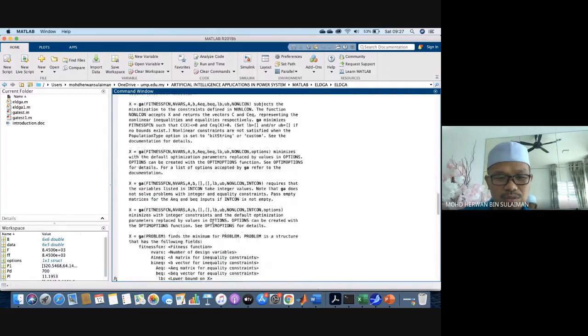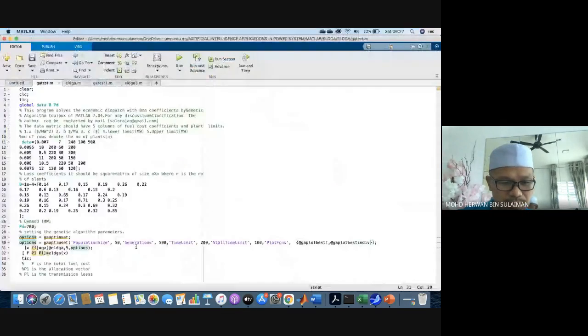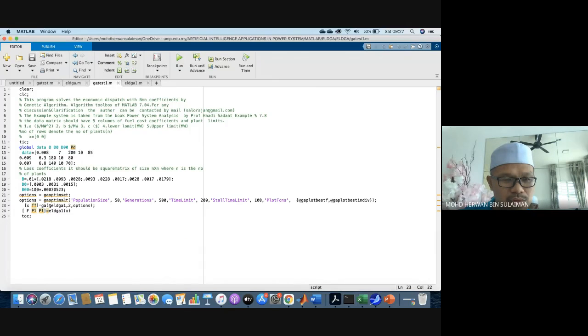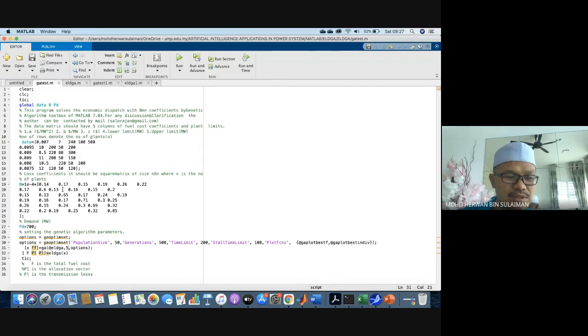Okay, so let's take a look back at what this guy has done. It's just 5 and options. What are the options we embedded here? I'm not sure what the 5 is, let me check. Because we have 6 generators, right? 1, 2, 3, 4, 5, 6. Wait, this one, 2. I think this one is okay. I know: 5, because even though we have 6 generators, one is what we call the slack bus, slack generator. That's why I use 6 minus 1. So this GA function will find 5 results and the 1 is the dependent result, in order to make sure that you obtain the 1 as the slack bus, slack generator.